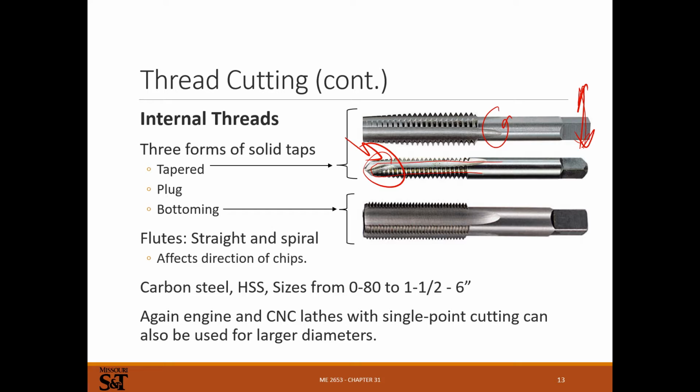You can do this in a lathe, where you hold the part in a chuck and lock the spindle down so it won't spin, and then use the tailstock. Your tap handle will usually have a centering hole in it that you can put a dead center or a live center on, and keep these things straight, at least for the start, if not to finish the whole operation. You can do this in a mill too, where you use the quill to get these things started.